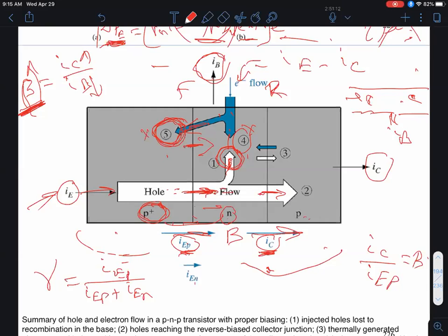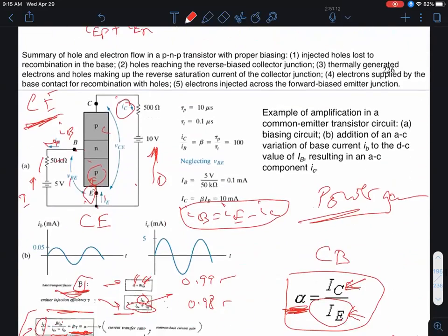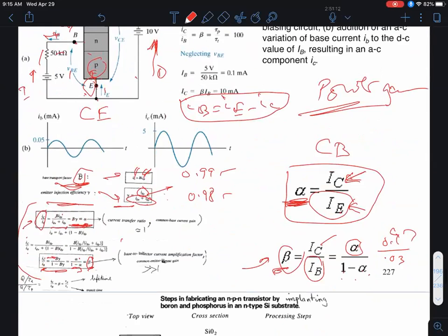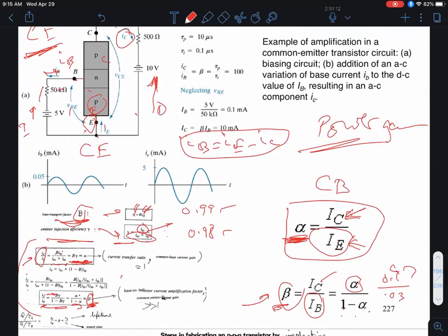That's my emitter, that's my collector, and the tiny leak is my base. What I'm saying is, by controlling that leakage current in the base, I can modulate a huge amount of current flow from the emitter to the collector, right? I mean, that's basically what I'm claiming in terms of the common emitter current gain, right? I hope you get the question that I'm asking myself.